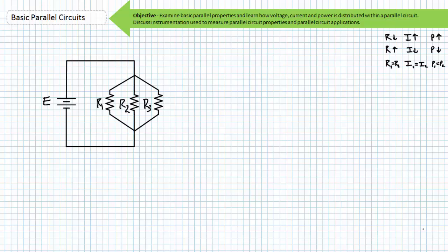Ammeters measure current through a single point and are employed in series. To measure voltage across a purely parallel combination of any number of elements, a single voltage measurement would suffice. Voltage across elements in parallel is the same. Isn't that convenient? What's not so convenient is the use of an ammeter within a parallel circuit.